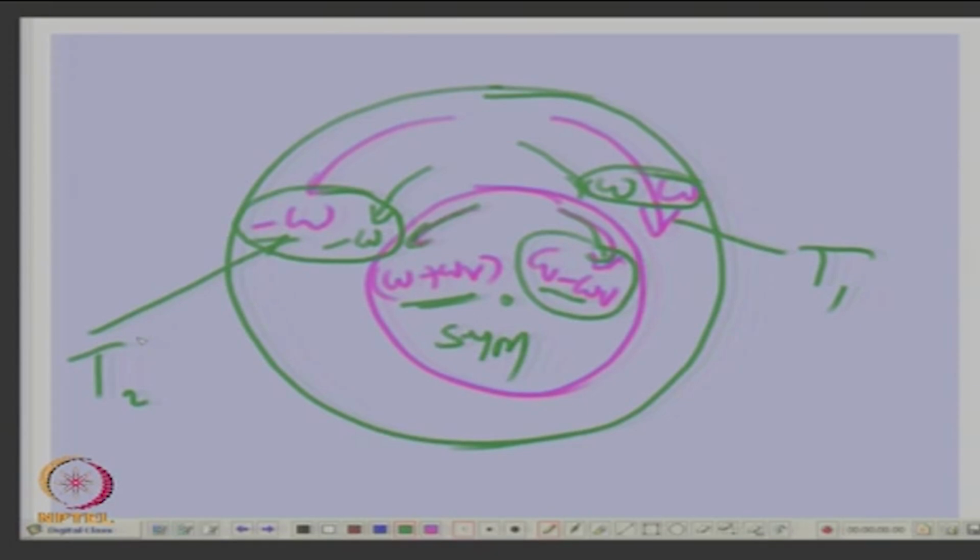There is no way a further backward field can be created out of the induced currents. So there is no further induction into the stator. So the only frequencies you will have are f plus or minus fr, and it will terminate at that point.